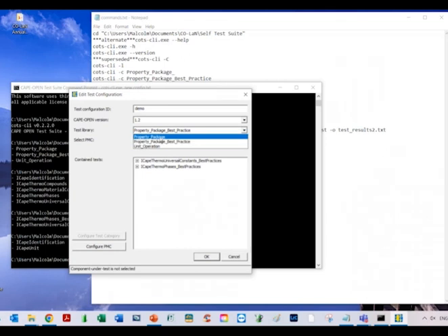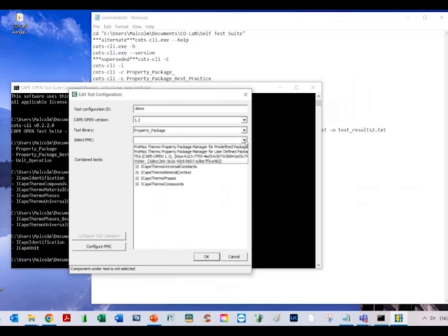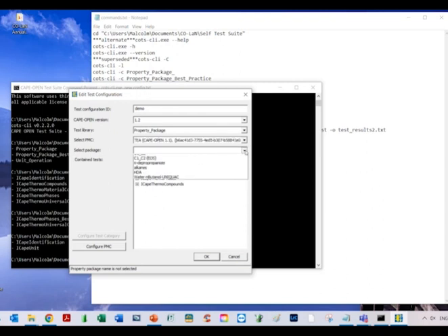I'm going to use the property package library and I am going to select T. All the 64-bit property packages on this machine should come up in that list. And I'm going to choose alkanes. I don't want to configure the component. I could go into the actual process building component and configure it. And if any of these require a temperature or a pressure or both, I can configure the test category as well with temperature and pressure. But none of these need that. So that's all I need to do.